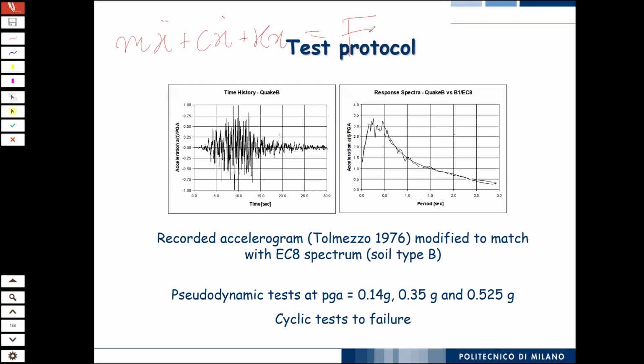But generally speaking, strain rate effects are beneficial to the strength, because we say that if loading comes with a very high strain rate, the stress waves do not have the time to find the weak path. So generally, if you perform dynamic tests on materials with the split Hopkinson bar, the strength that you get is higher than the static strength. That is the dynamic amplification factor. So you have pros and cons.